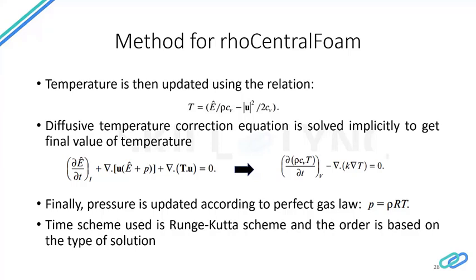By that I mean anything that is not happening at clock time or anything that is less than 1 second is considered faster than real time analysis. And for time schemes, the higher order schemes are implemented when your delta T is especially very low, where you require high resolution, i.e. your field variables change drastically over very short period of time.